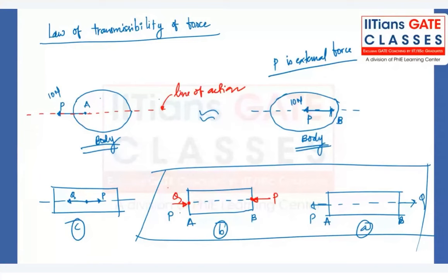So that is something we cannot capture whenever we talk about the internal forces. External forces you can do. Whenever you are finding the internal forces, only then you cannot apply this, because you cannot say whether the forces are tensile, compressive, or no internal force. That conclusion you cannot make. But if external forces are there, then you can make some conclusions, because you can easily move the force from one point to another point on the line of action.